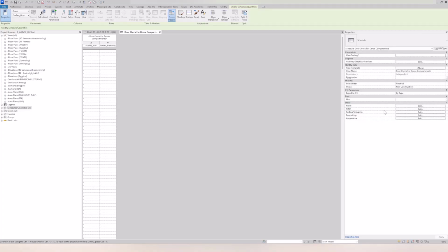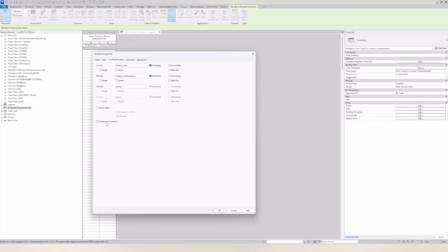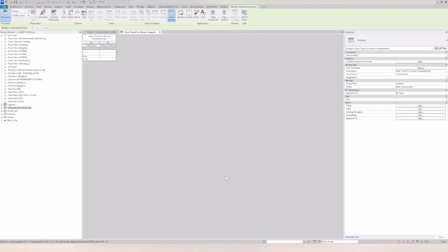and we will remove the sorting and grouping to not itemize every instance, we can see here there are doors that have a host requirement and do not have a fire rating requirement. There could be several reasons. It might need to split the wall, so we got some false negatives, but at least now we can quickly and easily figure out which objects we need to take a closer look at and check the data that has been received from the specialist.